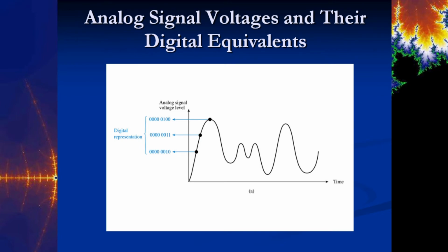So this is a good example of what you might see if you're going to convert an analog signal to digital. You have to have some type of scaling mechanism, and we'll later find out that that's called resolution. How many bits do you have to represent this signal? Well, it looks like in this case we've got an entire byte here. We've got 8 bits, so you could have from 0 to 255. So 256 different points from whatever the tallest point is here to 0. So you could chop that up 256 times and get pretty close.